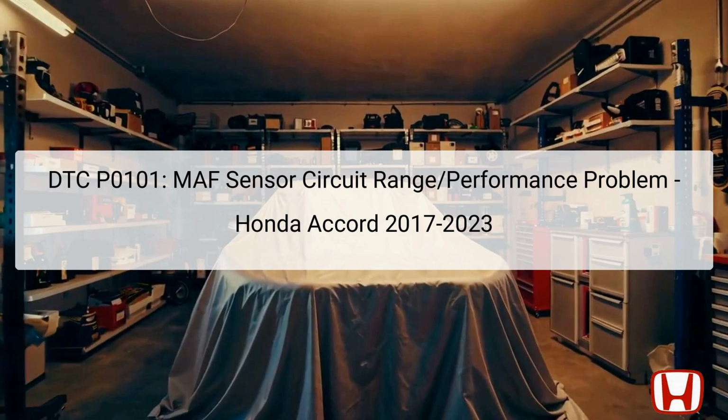The MAF sensor's location is generally found in the air intake system, typically right after the air cleaner, which allows it to assess the incoming air that will mix with fuel in the combustion chamber. An issue flagged by this code often indicates that the MAF sensor is unable to provide accurate readings of the air entering the engine, leading to potential engine performance problems. Proper function of this part is essential, as any discrepancies can affect fuel economy, power delivery, and emissions.